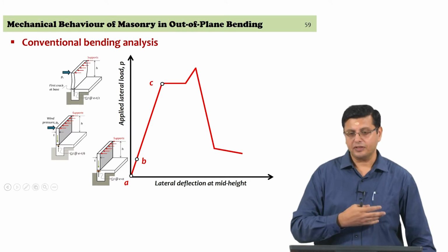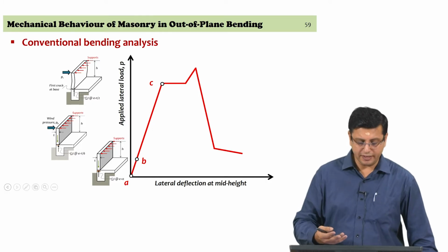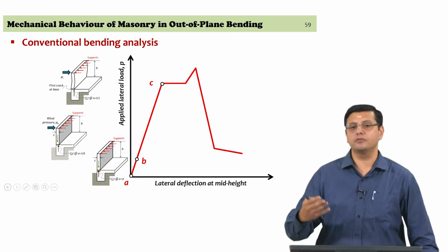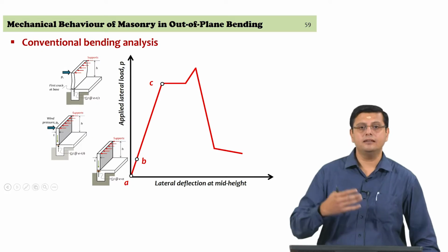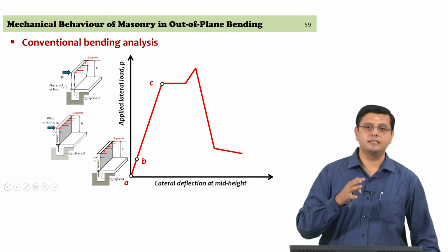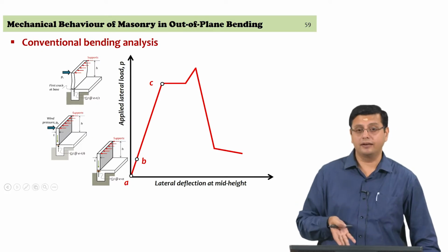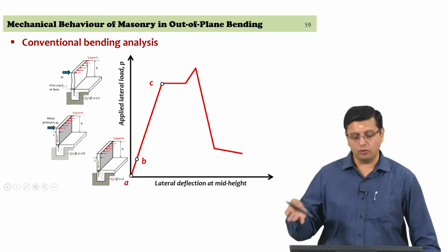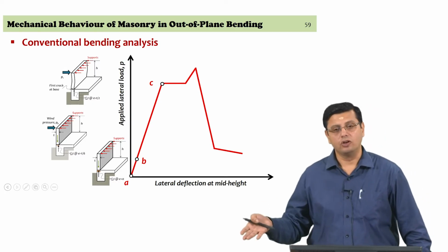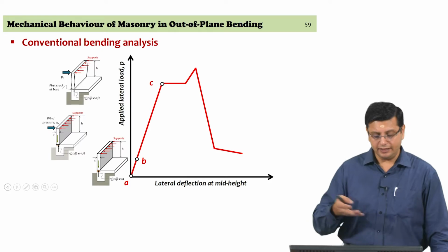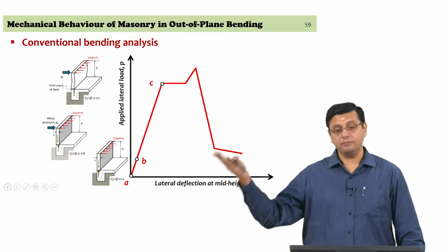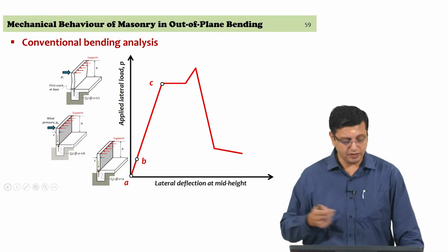And as the lateral force continues to increase, we see the initiation of the first crack, right, and that is the first inelasticity that occurs in the system under this assumption, and you should therefore, as the load resistance continues beyond that, get a drop in stiffness, a reduction in stiffness of the system.